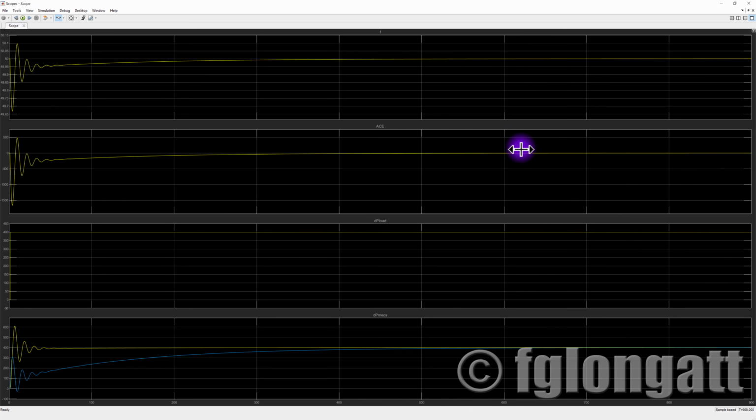But let's see the details here. That is where things start to be interesting. As you can see, we use the same load change, 400 megawatts. And you can see how the frequency goes down, and there are some oscillations over here. But before 100 seconds, the AGC is kicking in. The AGC identifies that there is an ACE, I mean, an area control error, and the controller starts to change the reference of the governor. And what is the consequence?